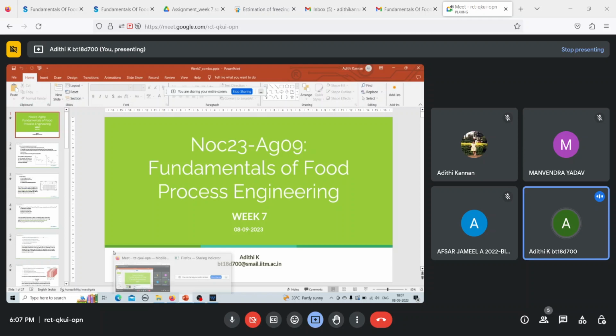With this, we can calculate delta H1, delta H2, delta T1, delta T2, and substitute in the freezing time equation. So first we'll calculate the mean freezing temperature, Tfm. Tfm is equal to 1.8 plus 0.263 into minus 18 degrees Celsius, which is your final temperature at the center of the food product, plus 0.105 Ta, which is the temperature of the air being blasted in the freezer.